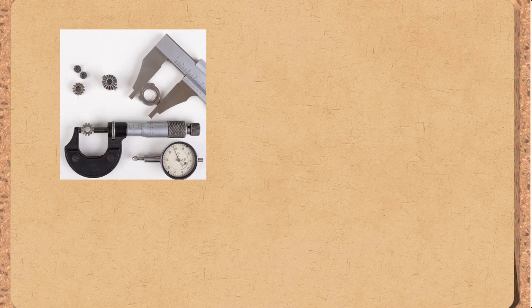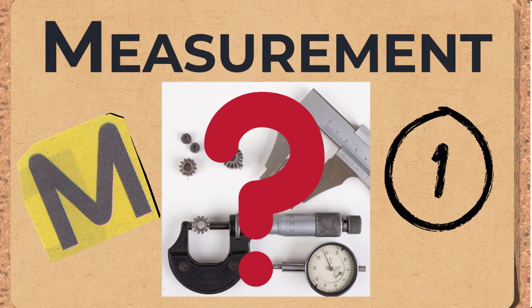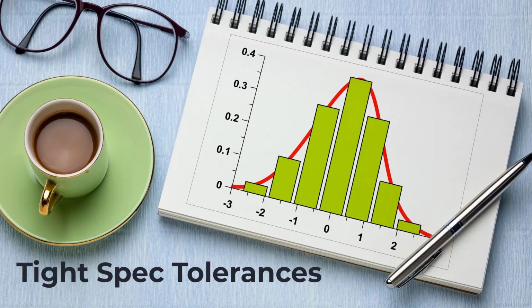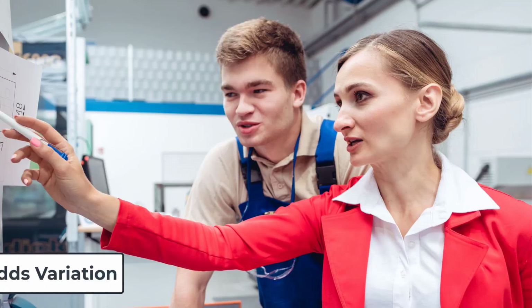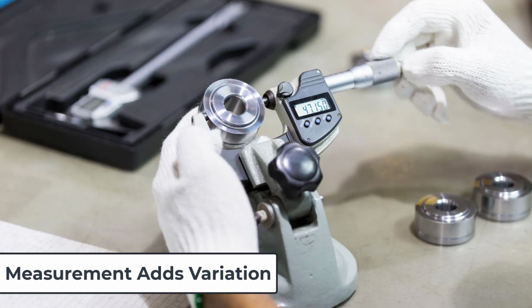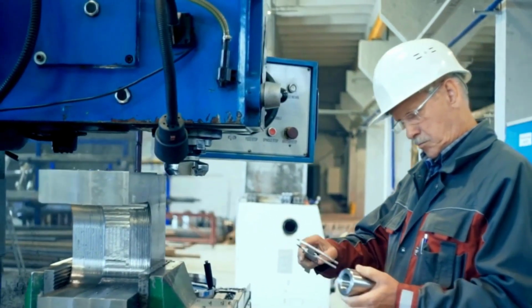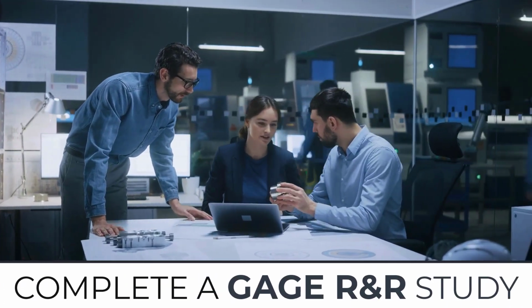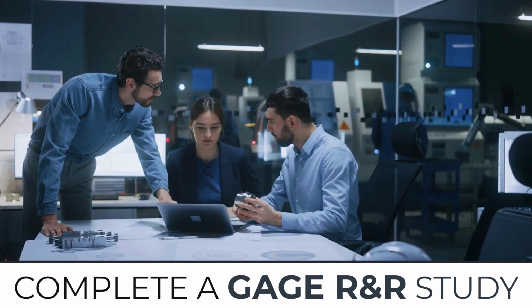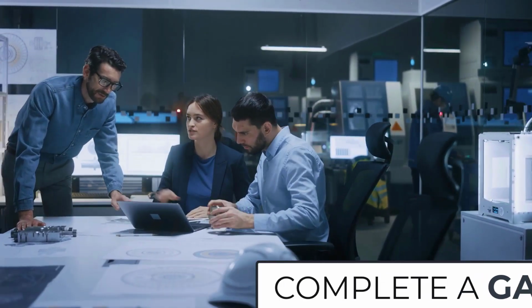Our first suspect is measurement. You want to know how much of the total variation comes from your measurement system. When specification tolerances are tight, such as in a precision machine shop, even well-trained inspectors who use precision gauges can be responsible for a high degree of measurement error. Solve this mystery by doing a gauge R&R study. A gauge R&R study is going to be like doing a DNA test in a crime lab. It's going to help you determine if your measurement system is a variation culprit or not.